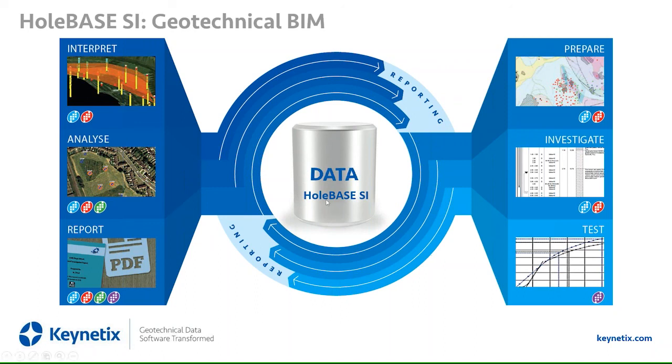So as we get the data into HoleBASE, another thing we can do is start scheduling all the lab tests that we want to do on it. We don't need to write it down on bits of paper. It's all done centrally in the data management system, and then we can send that off to the labs to perform our tests. We import all the data from our labs, get it all into HoleBASE again. So at a click of a button we can generate reports, charts on that information. We can start analysing it, trying to work out what the site characteristics are, what's going on in the north end, the south end of the site, and start doing the 3D visualised interpretation of it.